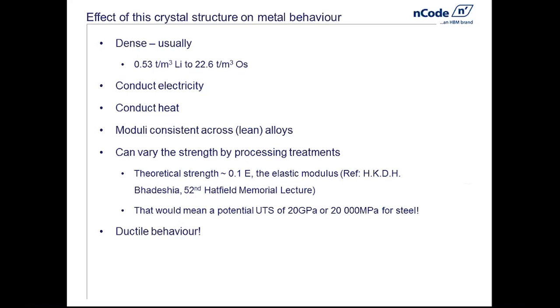I needed to dig out a figure of what the theoretical strength of these things was, and the best I've come across, the most compact, is that comment by Harry Bhadeshia in a Hatfield Memorial Lecture, that you could get up to a tenth of the elastic modulus. Now, this of course doesn't happen in practice, because you would then have a potential UTS of 20,000 megapascals, and that's not reality.